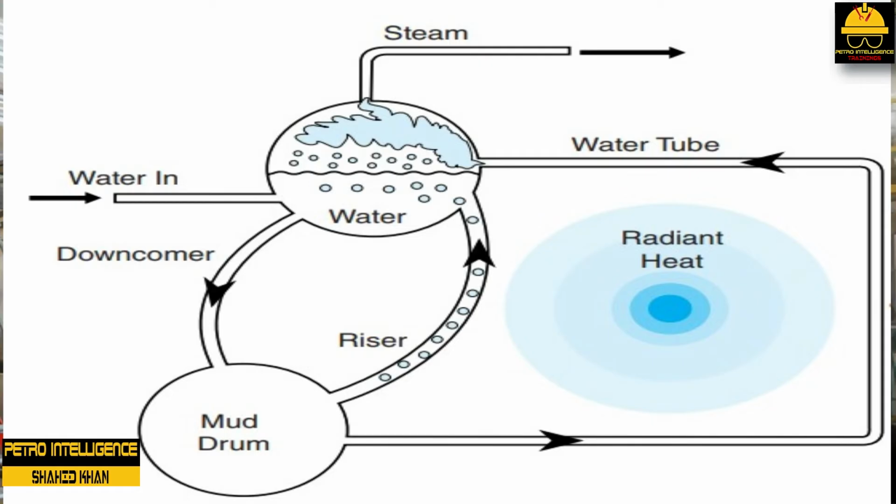Water temperature increases at programmed rates. Pressure begins to increase. Steam may initially be vented to the atmosphere. As the temperature of the water inside the generating and riser tubes increases, the density of the water decreases and initial circulation is established. Bubbles begin to form and rise in the water, increasing circulation and pressure as shown in the picture. This circulation rate can easily reach 2 million pounds per hour. At this point, approximately 65,000 pounds per hour of steam is being produced.